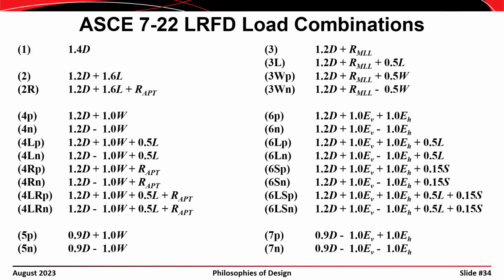Finally, when we consider all the different variations of the load combinations, the possibility that some transient loads may not be acting, and consider the directionality of the wind and the seismic loads, we are left with these 27 permutations of the original 7 load combinations.